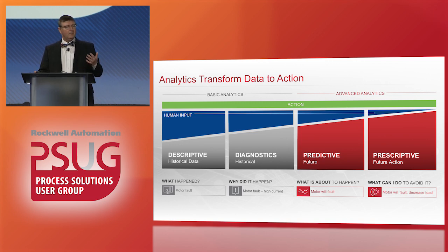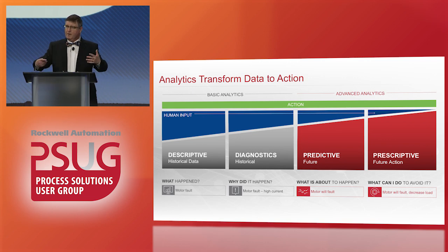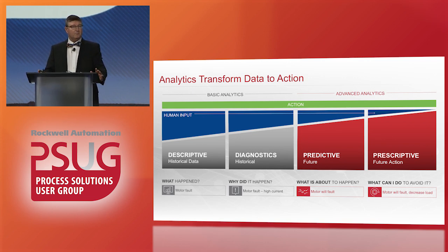If you think about alarm limits, I've got a high temperature and I'm going to get an alarm limit. Advanced analytics is looking at the problem from more different data sources, and it's saying, well, at this load, with this product grade, with this age on that compressor, the temperature is higher than it normally is. And so it's going to tell you something's wrong earlier. And that's one of the advantages of advanced analytics, is that earlier knowledge of problems or opportunity.